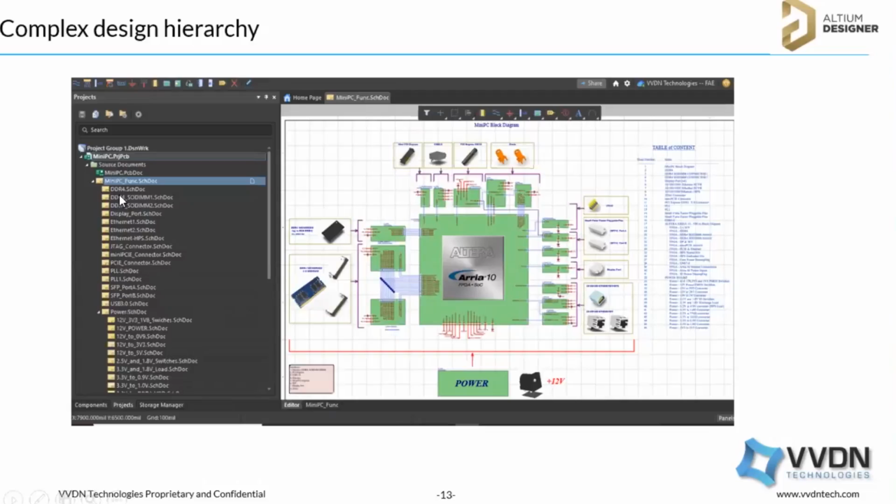If you have 100 sheets, sometimes 60, 20 sheets or more, right? So you can define that hierarchical design, like what is the main top level sheet and which is under the child. For example, here in the C, you can see under power, all the power schematic sheets are there. Like that, you can make your own high speed interfaces. Under that, you can keep the interfaces. So like that, it will be easy for them to verify as well as understand, and design wise it will be very easy to create the classes and others. Okay,